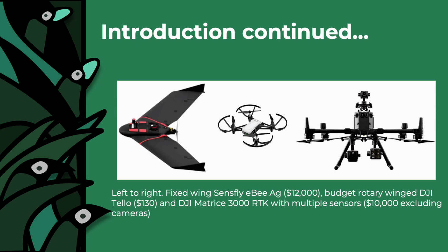It can be addressed in two ways. First, the use of professional-grade UAVs equipped with better quality GNSS receivers capable of differential correction, or two, establishment of ground control points, GCPs, prior to the UAV flight. GCPs are points on the ground that are identifiable in the images obtained in the drone survey and which have known geographic locations.